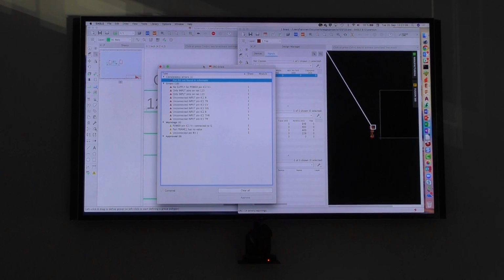There are some situations, if you connect, for example, in the layout editor, GND and a plus point once, then it could get complicated to figure out where to cut the nets so that it fits again to the schematic. This can be challenging. It can happen that you say, okay, I have to delete the whole signal and do it again. This might happen, but it's recoverable with a bit of manual intervention.